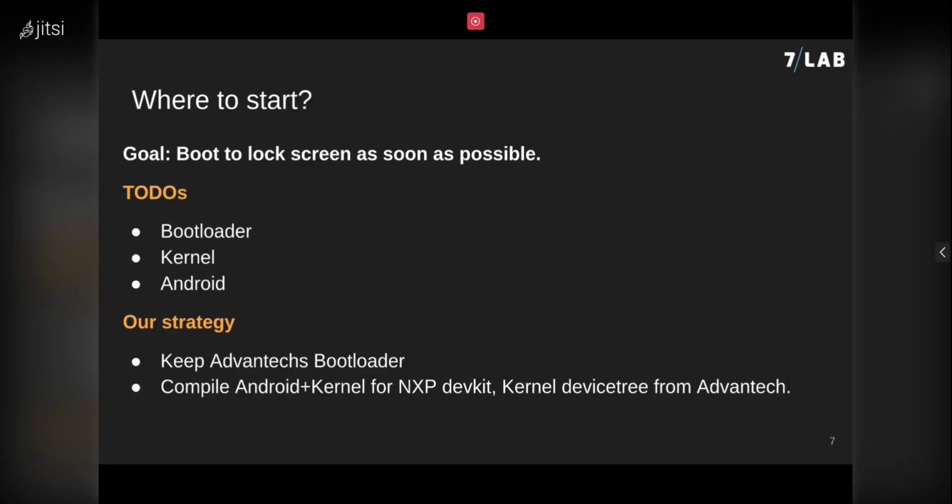For example, we had to disable Android Verified Boot. We had to add a few custom command line parameters, which newer versions of the bootloader add automatically. But that was very minor, and you can just iterate through that to see what's needed, and then it boots after you added 2 or 3 parameters. So that's definitely, after the fact, I can still say that I would recommend doing it this way, because it gets you to the goal pretty quickly, and you don't have to understand the hardware from the beginning. You can just try what works and then improve on it later.